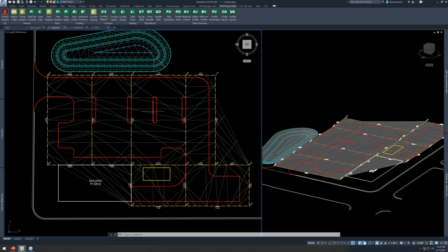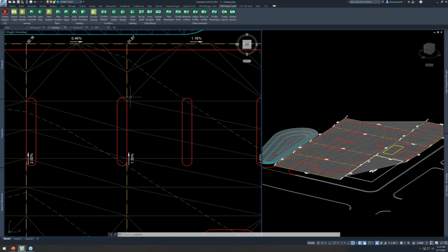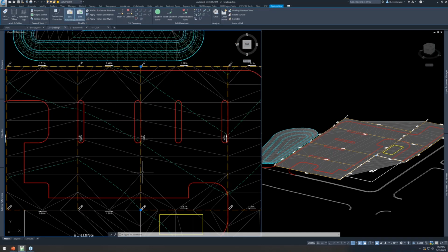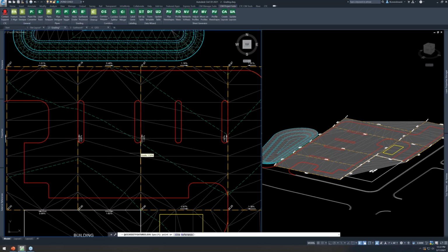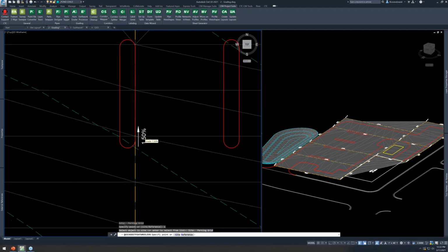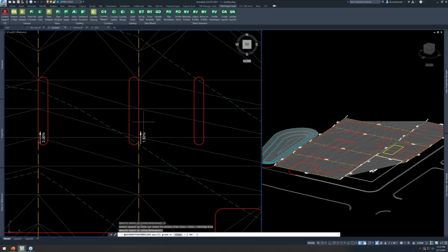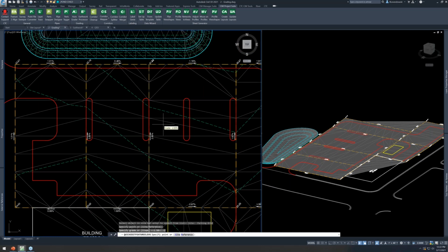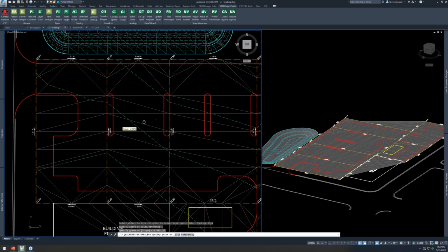When we get the curve grading done, we'll put spot elevations in there. But these are grade and elevation segment labels that allow me, as I'm manipulating this grid surface, to come to here and let's say grab this feature line, and that's currently at 1.5%. Let's say we wanted to go at -2 instead, and it gives you that immediate feedback as you're working with it. Now, I put these on the grid lines. You can put them on any feature lines you want.